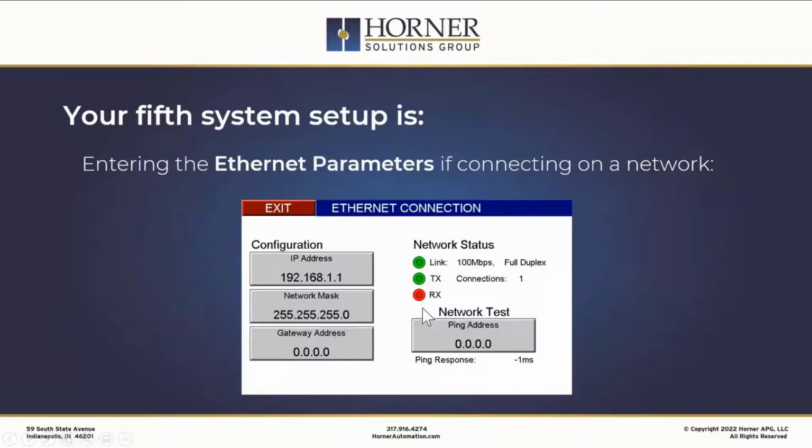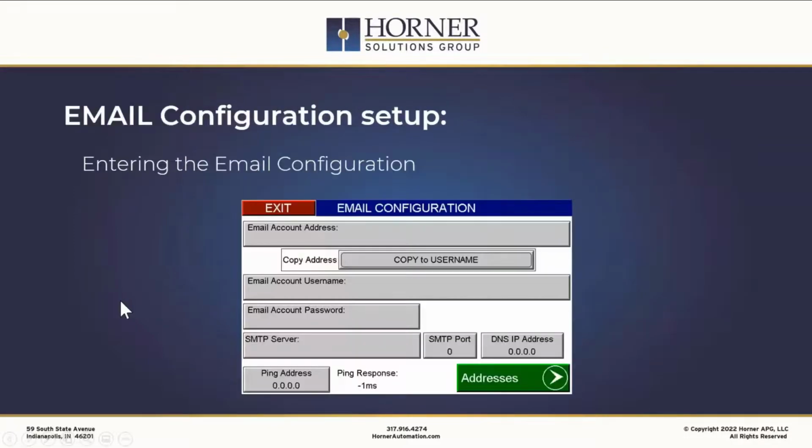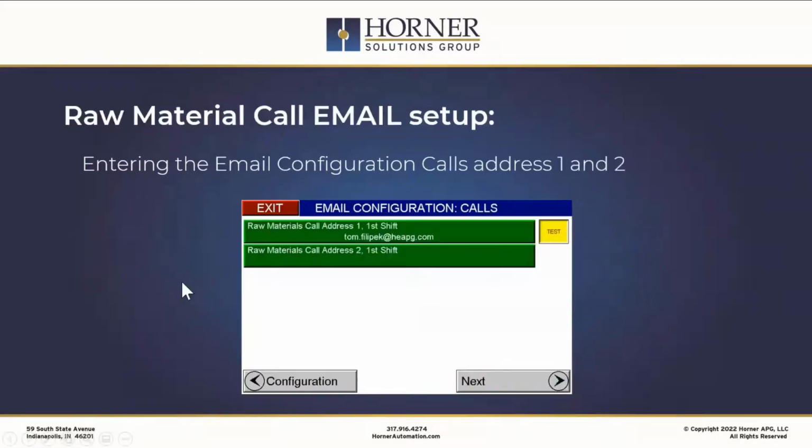The Ethernet configuration is where you go in and assign the IP address for this device. And this is where you need to put everything to make it connect up to the data concentrator, as well as for the IT team to know how to go get FTP file data, that type of information. And then this is the email setup if you're going to do it as part of this, as opposed to the Excel utility product. So you set the email up.